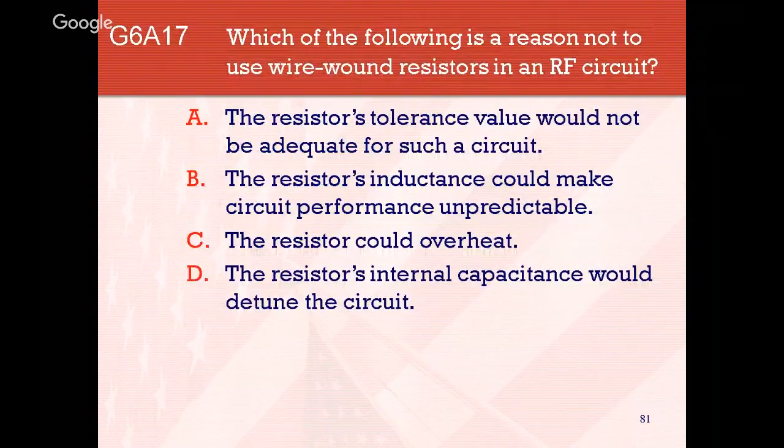So, which of the following is a reason not to use wire wound resistors in an RF circuit? You've got to remember this. You don't want to use these in an RF circuit because they are wound, and in essence, in an RF circuit, they act like inductors and could affect how your signal is routed through your radio. So the answer to this is B. The resistor's inductance could make circuit performance unpredictable.